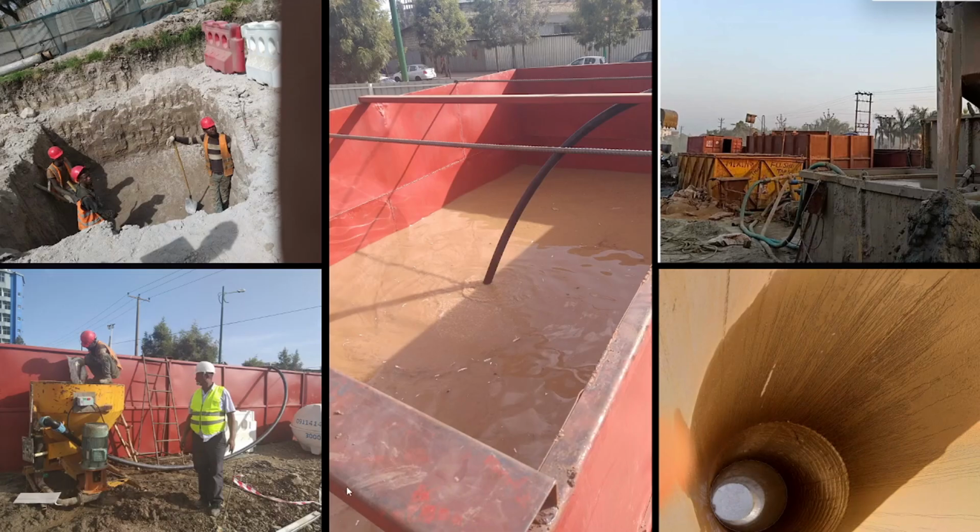This is what we call the stabilization unit, or how the mechanism works. Obviously, we are going to mix our slurry material, the bentonite, using stage 1 here on the tank or stabilization unit. After mixing, we pump this out into what we call the bore pile system.